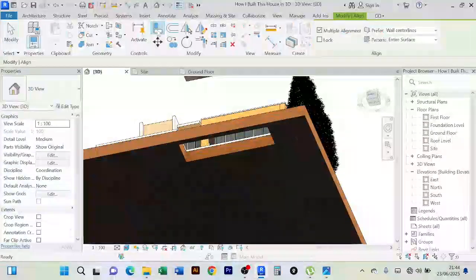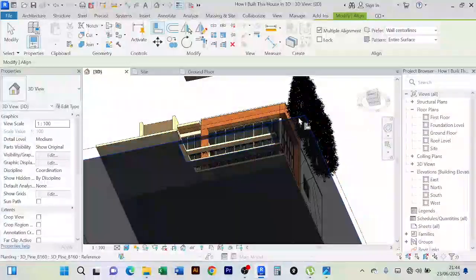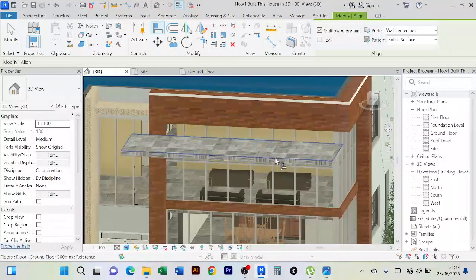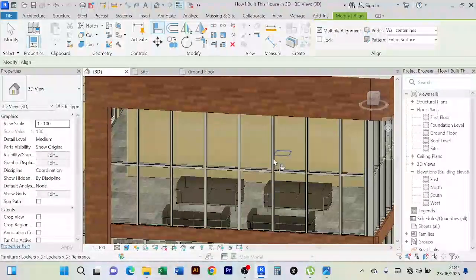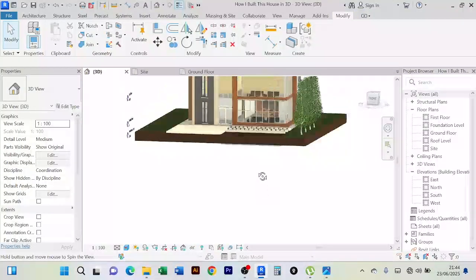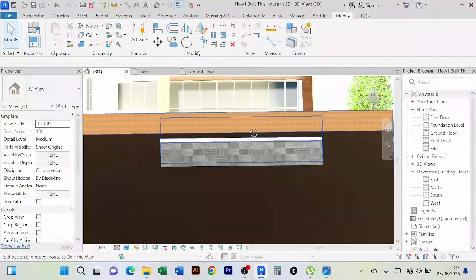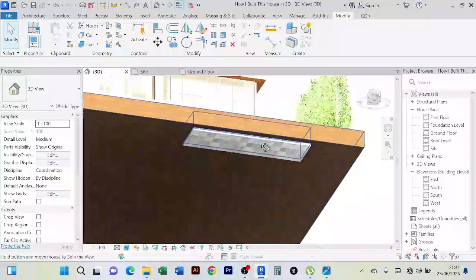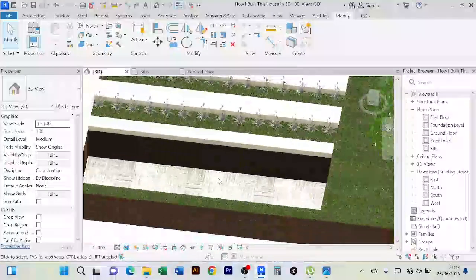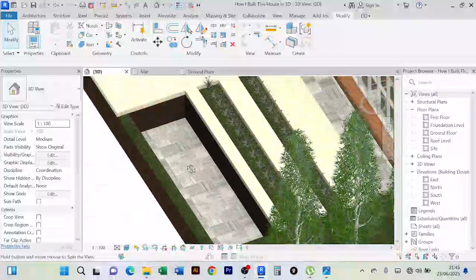You come to your align tool, then you pick this down side, then you align it with the top side of our floor, like that. Then when we escape, you realize this floor has come now all the way down here. See that? It is now down, and inside here you can now see your floor just like that.